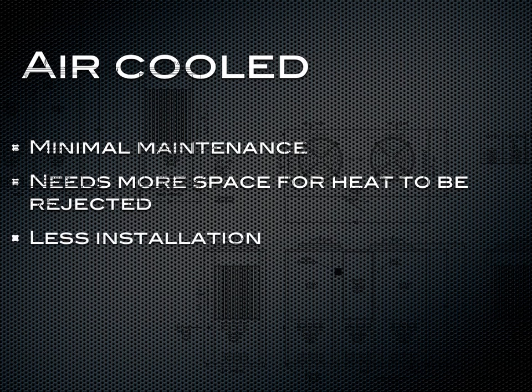There is less installation in the air-cooled chiller because they stand alone. They don't need a cooling tower or building water like a water-cooled chiller does. They are bigger in size compared to a water-cooled chiller because those condensers and fans are much larger than the condensers on a water-cooled chiller. They are more common because they do stand alone.